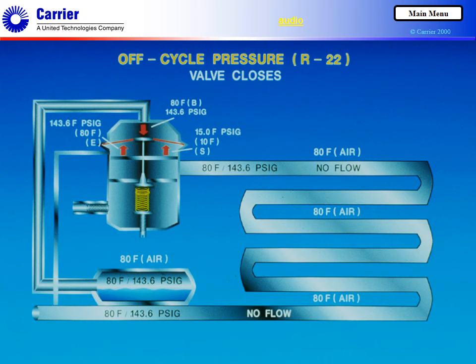When the compressor starts, the evaporator sends refrigerant vapor at 80 degrees Fahrenheit saturated suction temperature into the compressor. This continues for a period of time before the new liquid flowing into the evaporator brings the temperature down to a normal range of about 30 degrees Fahrenheit to 50 degrees Fahrenheit for comfort air conditioning work. The high suction temperature causes excess compressor power consumption, which will cause compressor motor overload. If compressor motor overload continues, it also will cause compressor damage due to high discharge temperatures.